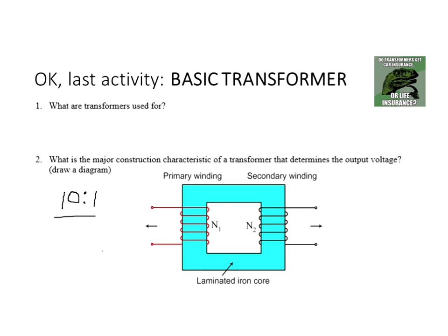I'm going to risk telling you that any transformer you see on the CET or employee entry examination most likely would be a step down. Now, if you're going into the power distribution industry, you might see step-up transformers, but generally about 80 or 90% are step down. So all you need to do is divide by the number in the turns ratio to actually get the voltage on the output.